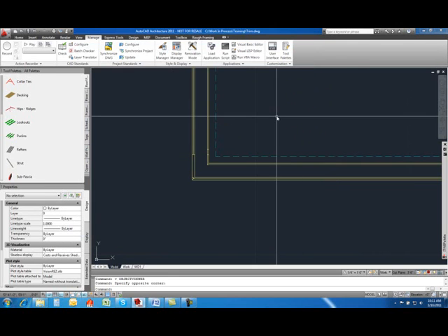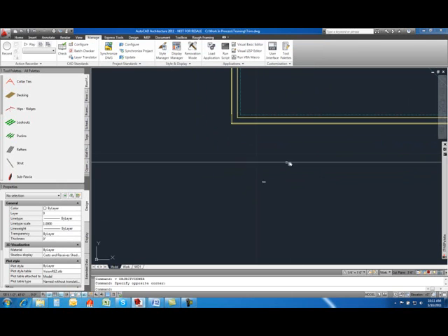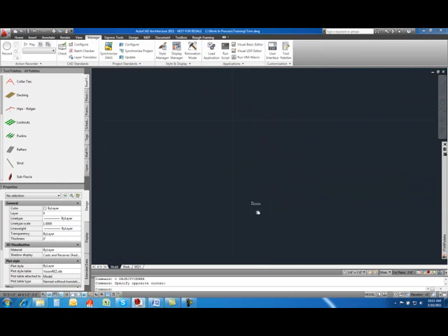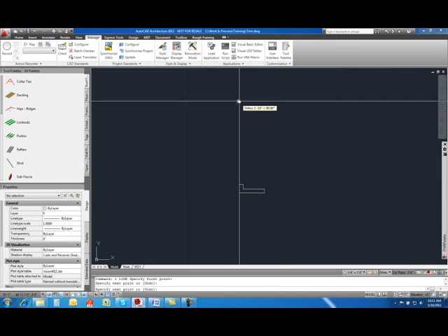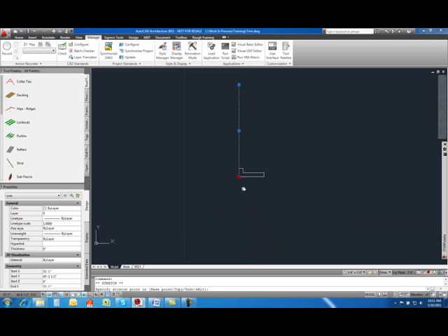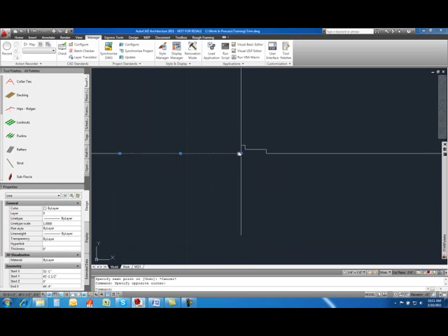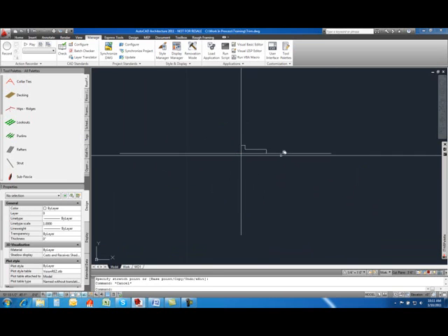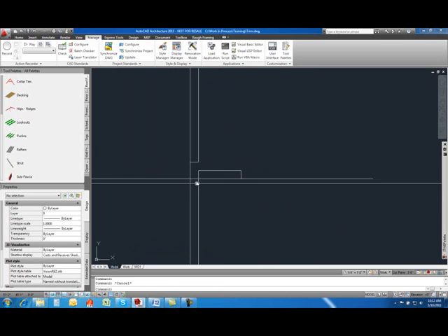Now, one of the important points that I didn't talk about too much is what the actual insertion point and rotation needs to be. Sometimes you'll mess that up, but typically think of it as a coordinate system when you're drawing your trim. If this is an XY plane, you want your trim to lay down with the insertion point at 0, 0 there, and this is going to be the top side and the bottom side.